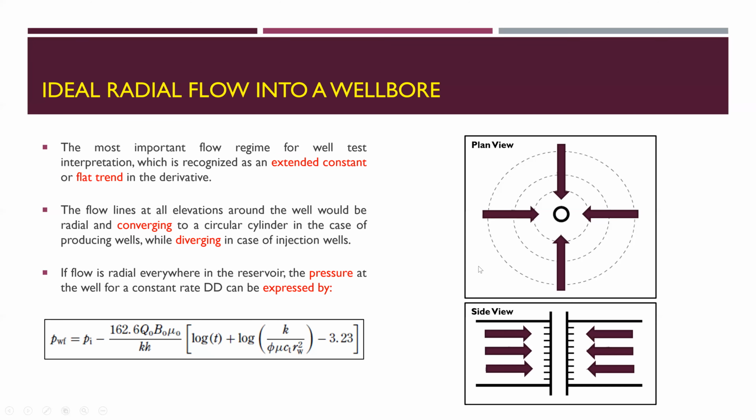Why is the radial flow regime very important for us? Because the diffusivity equation has been solved considering radial flow and constant rate.